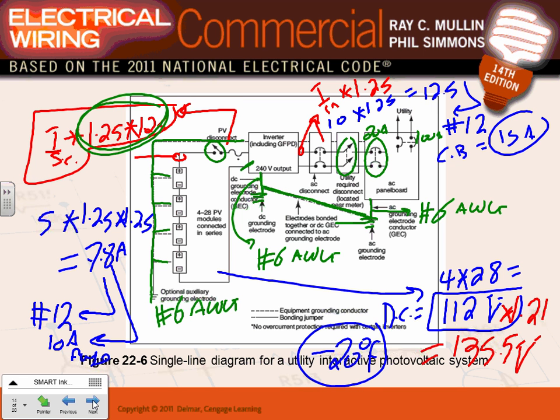Any comments, guys? Any questions? This becomes the rated voltage for your system. So the voltage has to be adjusted based on the temperature that you have. When you design the system, you have to adjust the voltage based on the temperature, period. Where did I get this 1.21, based on minus 20 Fahrenheit in Minneapolis? It's Table 690.7 in the NEC code book, on page 489.